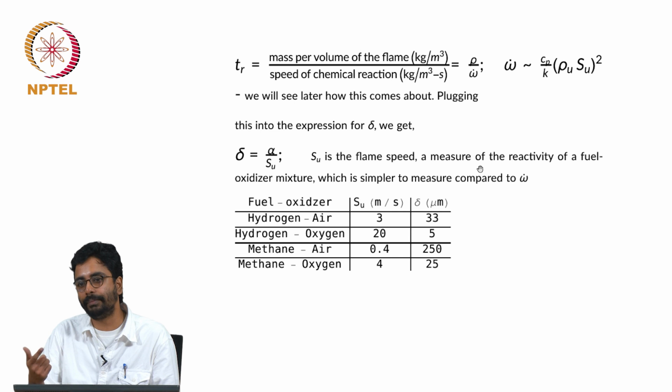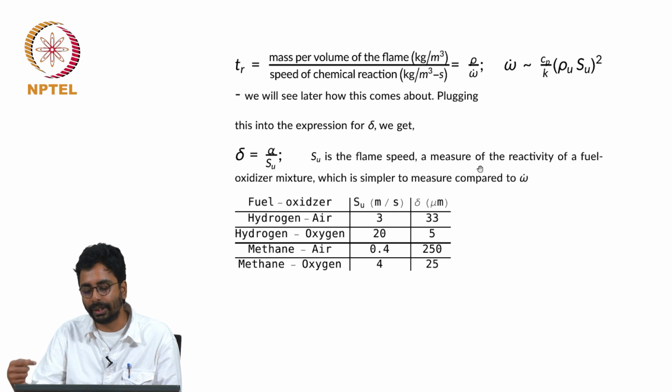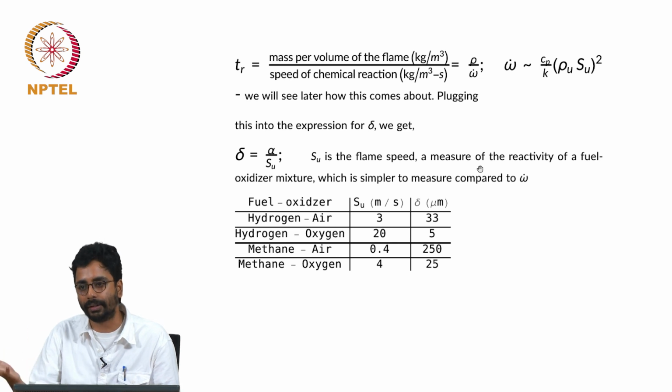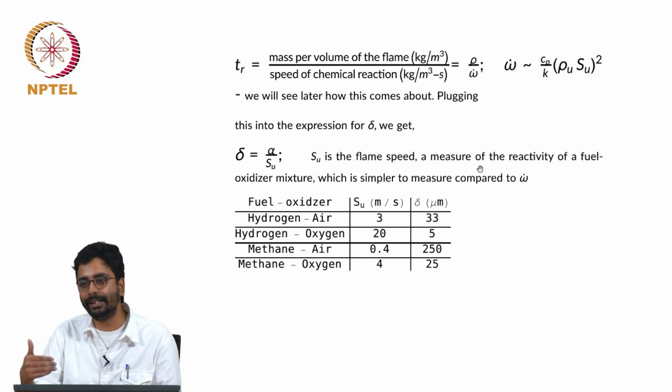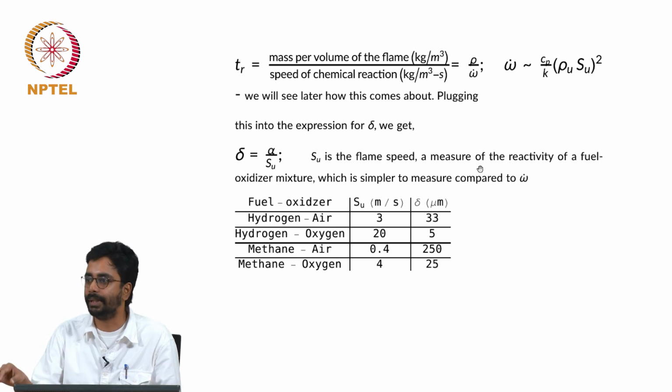The only point that I want to make here is that the smallest turbulent length scale is limited by the length scale and time scale at which processes become dominated by laminar diffusion based dissipation. That is the Kolmogorov scale, and that scale is still much larger than the volumes where relative fluctuations can become larger. Any other question?